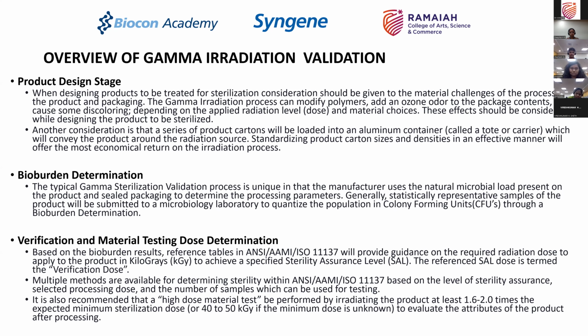The other consideration is that a series of product cartons will be loaded into an aluminum container called a tote or a carrier, which will convey the product around the radiation source. You saw that conveyor in the picture where the load was moving through a zigzag or hairpin curve path. In such a situation, you are going to load your cartons or whatever your products are into an aluminum container, a metal container in which you will load the products, and then you will bombard it with the rays.